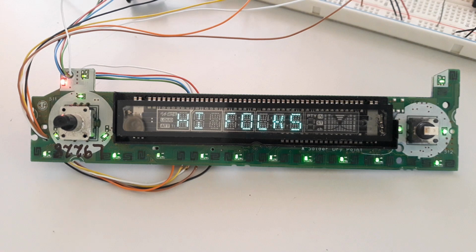We can use the command mode to define the M0, M1 and M2 equal to 000 to write to all three grids simultaneously. The method is very clear in the driver datasheet, and I use this process to write to the three grids at the same time in the process of finding the segments.